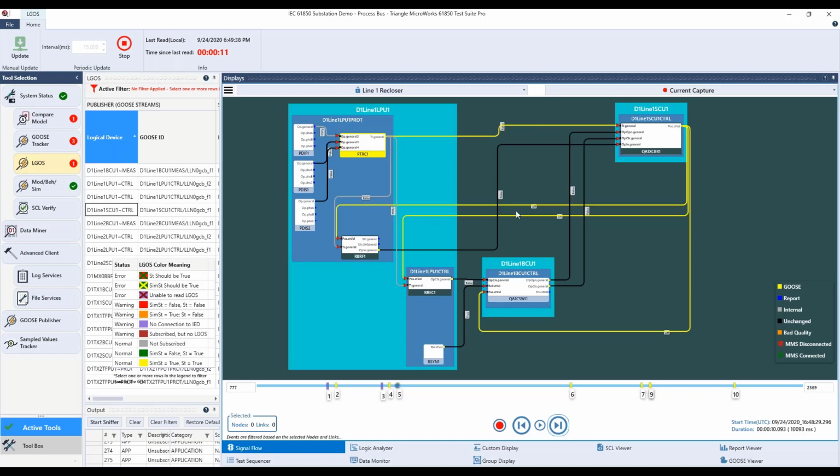The next thing now is the breaker off, and before it has been initialized, the recloser will, after the reclosing time, send a reclose signal to the CSWI. The CSWI itself will send the close signal to the breaker.